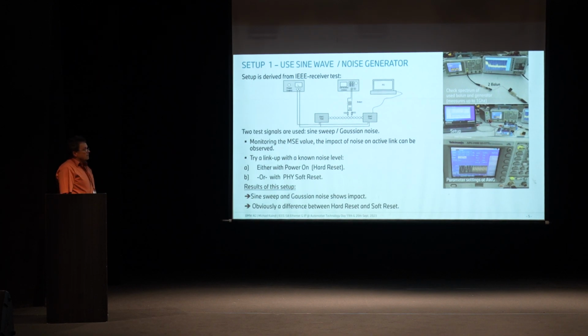During the test, I look at whether noise has an impact on the link. I set up a link with a certain level of MSE, then do either a power-on reset or a soft reset. A power-on reset means turning it off hard, and a soft reset means communicating via the PC to the tool to establish a new link. In this simple setup, I saw some results.